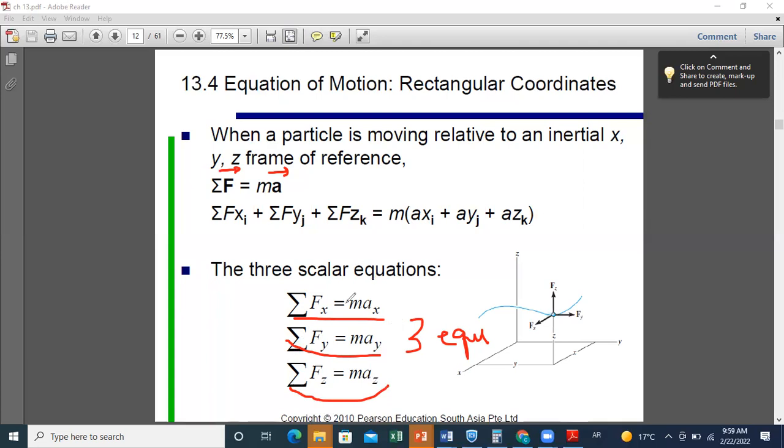So we can vary the problem input, and always, to be able to solve just by these 3 equations, we should only have 3 unknowns. If we have more than 3 unknowns, we should look at an additional relation. Sometimes you can get it geometrically. Sometimes you can get it, for example, from a force relation. Let's say you have a spring, you have that the tension in the spring is equal to k delta L. So you can relate the spring stretching to the tension developed. So if you have more than 3 unknowns, you need an additional relation to close your system.